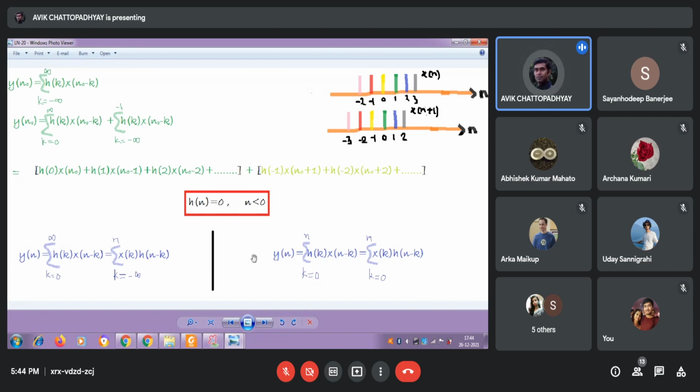Only the present and the past values of the input signal, which are already available, and only based on that can I do the computation of the present output. That much I can do. But real-time signal processing with hardware, please note, is not possible otherwise, as I have mentioned several times in the past in the class. Anyway, so this is about causality.